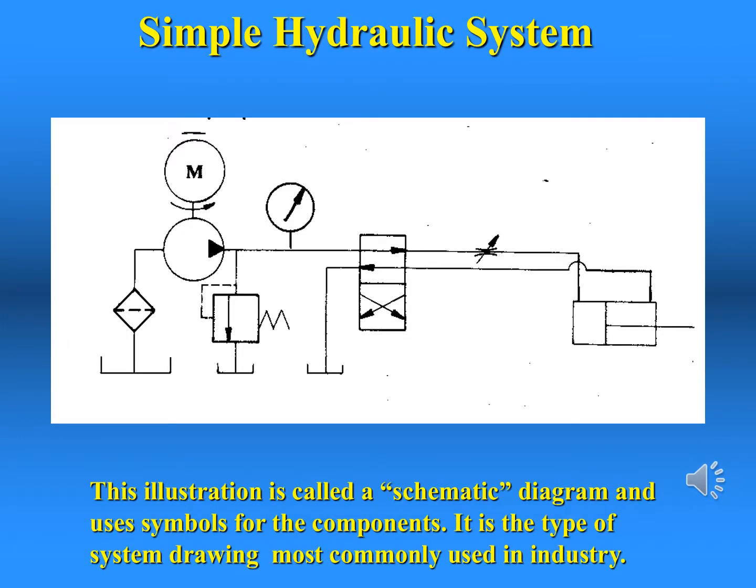This is a schematic drawing, also known as a single line drawing, of a hydraulic system. They read faster than any other types of drawings once the meaning and purpose of the symbols is known. The manner of reading is to identify the power unit on the left and then to trace the path of oil flow out into the system toward the actuator.